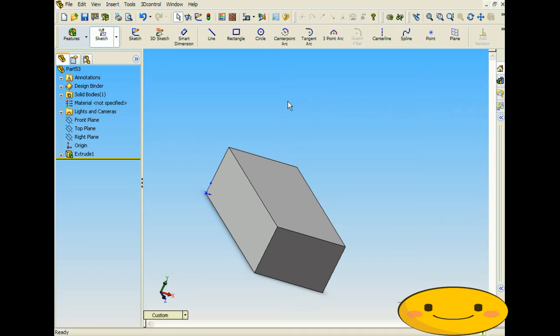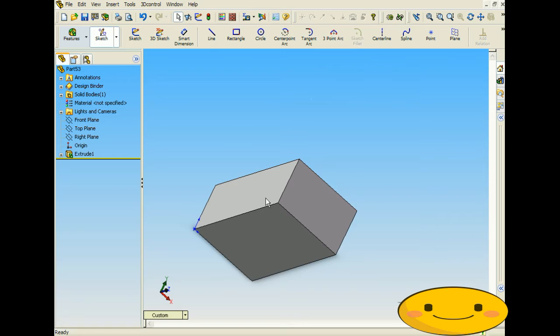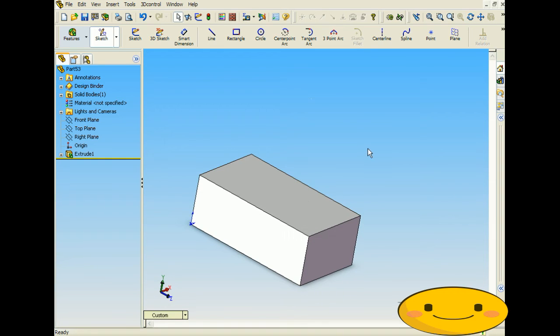So using this tool is the best way to measure everything within it, and you're able to measure something simple like, say, from this point to see how far that line is, or something more like from this point to this point, and it'll show you in more detail than just doing a smart dimension grab. And it'll also let you measure a single point and where it is in the coordinate system.